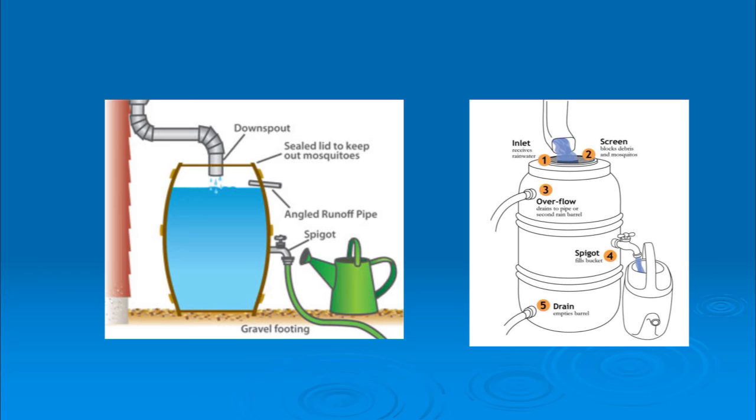At a hardware store, you can buy these grates. They're made for stormwater in your lawn. The company's called NDS. It's an 8-inch grate. I take that 8-inch grate and I put a screen over the inside of it, and I band that together with a hose clamp. That keeps the mosquitoes out. For the overflow, I just use a sump pump hose kit. It comes with all the fittings. So you cut a hole in the barrel and you just use the pieces from that sump pump hose kit, which is something you buy off the shelf. And it comes with like 20 feet of hose. So that's my overflow.